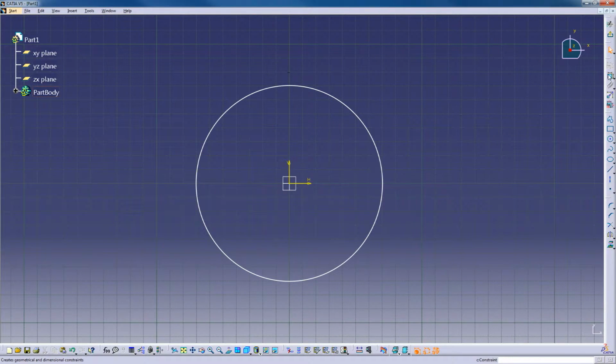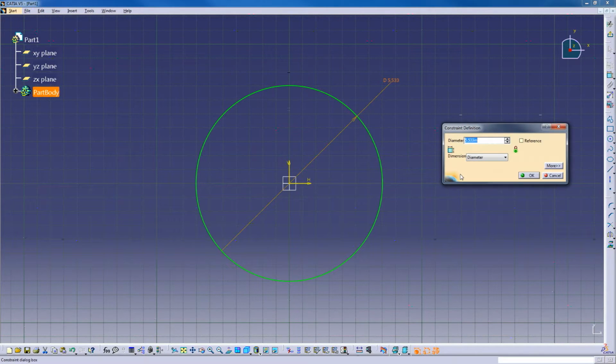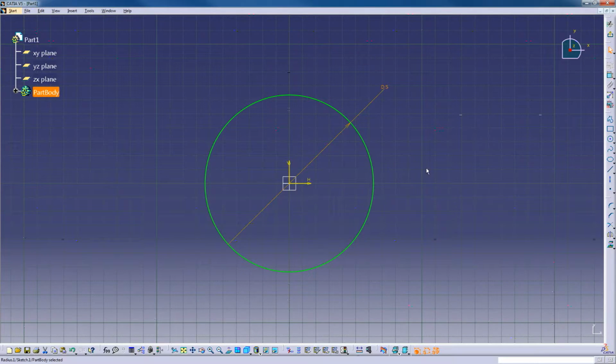So I'm going to pick this icon right here, and this is constraints, right? So we pick that, click on the sketch, and it brings out the dimension, right? If you're used to something like SolidWorks, you'll notice it doesn't pop up automatically to have you name it. So we double click it, and we say, okay, I want this to be just 5 inches. And it brings it down. The reason it is turned green, this is a really nice feature.